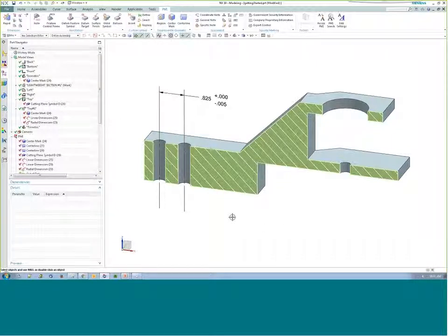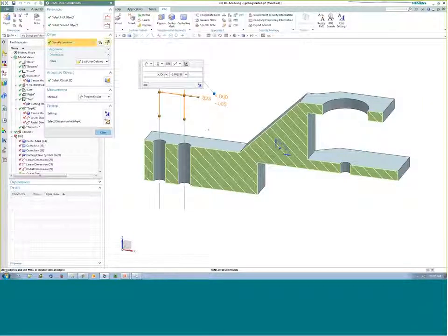But like I've shown, adding tolerances or changing the tolerance style or type is very much uniform with how you do it on a drawing if you're familiar with NX drafting. Double-click on the PMI element, and then you can change and update your tolerance style, the values, even some of the other display elements of that PMI component.